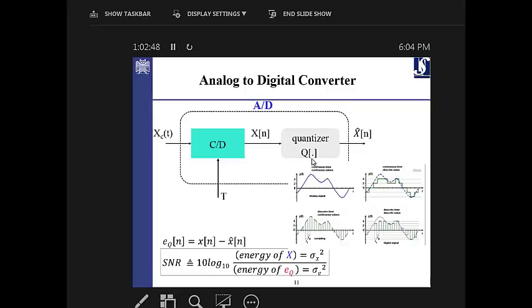You have to use any kind of analog circuits. For example, if you're using speech as a signal and you have a microphone, that microphone has some limitations for the amount of voltage that it can give you as input. For example, the company gives you a catalog for that microphone saying the signal goes from 0 to 5. What does it mean? It means that whatever the volume of the signal, it doesn't matter. It just goes between 0 and 5. If you want to do any kind of amplification, you have to do it inside the processor.